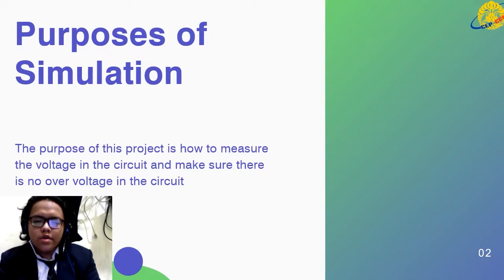Using direct connection between different components of the circuit usually results in many wires cluttering. This may result in connection errors and make it difficult to understand, debug, or modify the design. The solution to this problem is to use terminal connection.